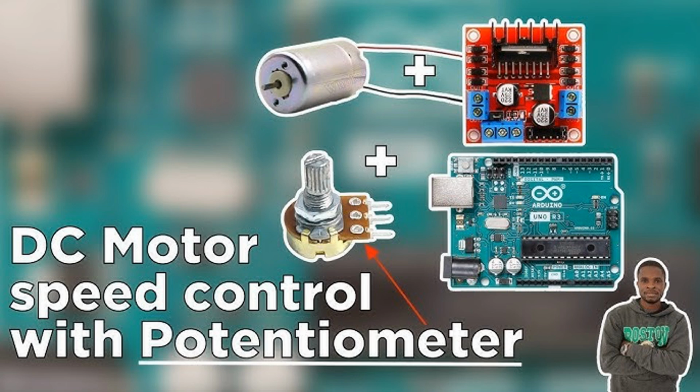Applications: Full-bridge drivers are often used in bidirectional motor control applications, while half-bridge drivers are found in simpler circuits where unidirectional control is enough. 6. Integrated motor drivers with protection features. Function: These drivers have built-in protections such as over-temperature, over-current, and under-voltage lockout to enhance safety and reliability. Examples: ICs like TB6612FNG and L298 have integrated protections and control circuits to handle various loads safely.